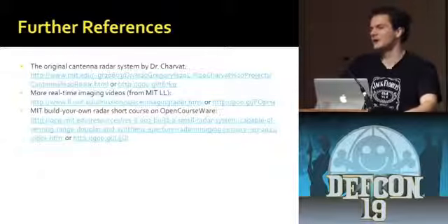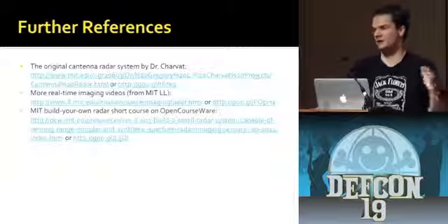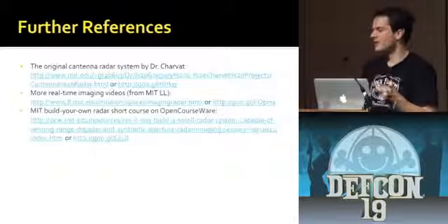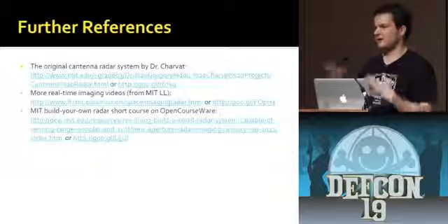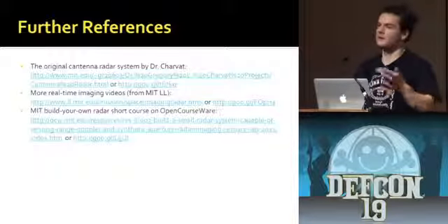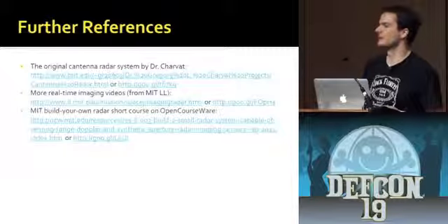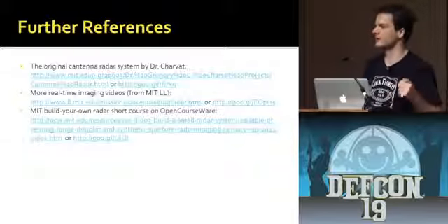On that microcontroller, it would be pretty hard. The processing power on this thing is pretty weak. It's just useful for quickly grabbing data. If you switch to a DSP or a nice ARM, or an FPGA, which would probably be the best option, you could definitely do that. It's not a very computationally intensive process. I mean, this is a Python script I was running to do the FFT.